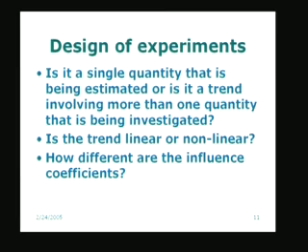For that, we have to look at what are the things we are doing. For example, in a manufacturing process, if you are trying to make some machine part, for example, you will be interested in the machine component and its quality and find out what are all the factors which are going to influence that. For example, in a typical process, you may be using a machine to either modify the shape or the surface finish or whatever it is. And in this process, I am going to use some parameters, like for example, the speed at which I am going to run the machine, the depth of cut, for example. So, each one of these becomes a factor. The depth of cut, the speed at which the machine is running, these become the factors, and the end product, the shape of the product or the size of the product or the nature of the surface of the product depends on these factors.